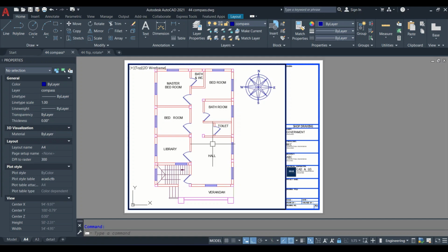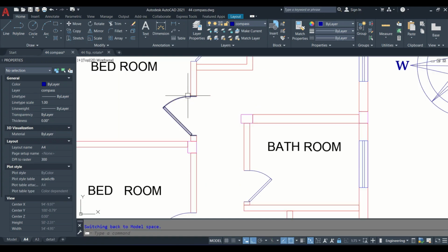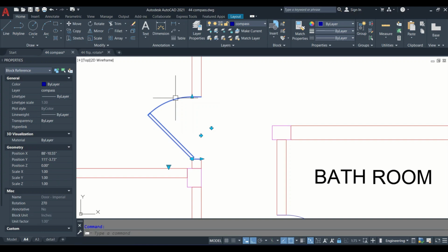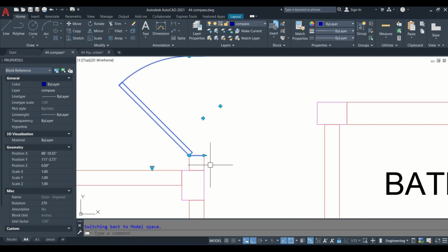Firstly, I want to show you some samples of dynamic blocks. As an example, this one. You click on it, then you will see the symbol of the dynamic block. This symbol means visibility. This symbol and this symbol look similar, but they are actually different. Then you can see a line above the triangular shape. Okay, this is visibility, and this one is stretch.